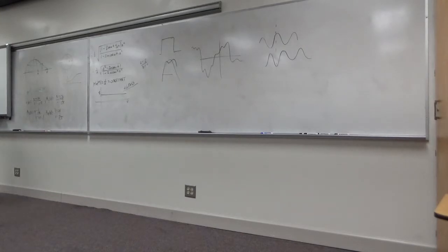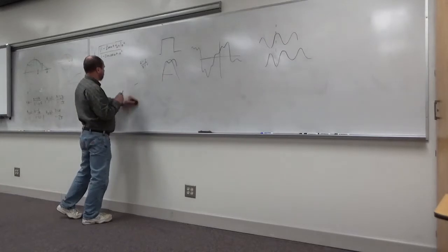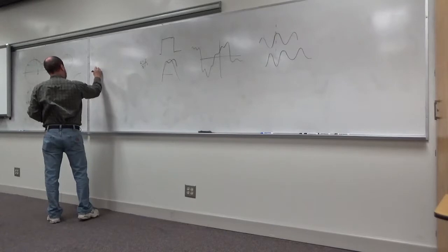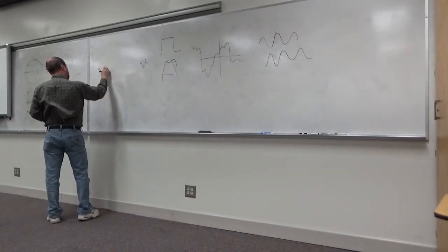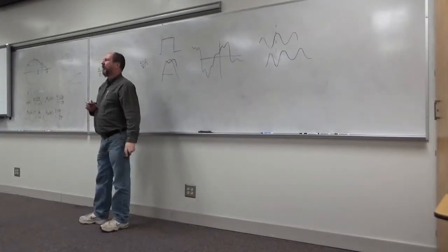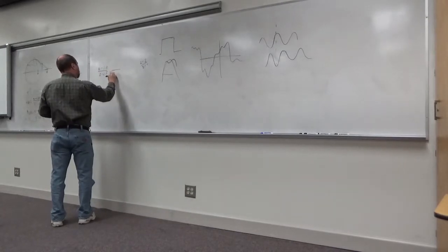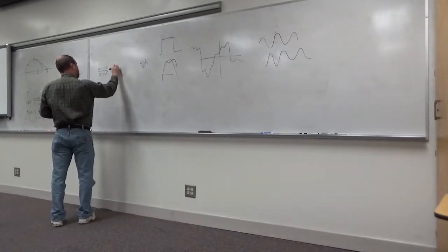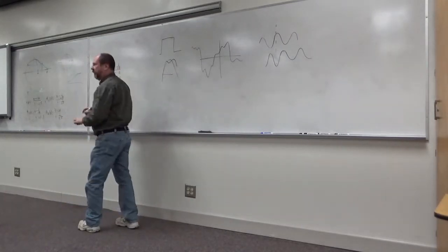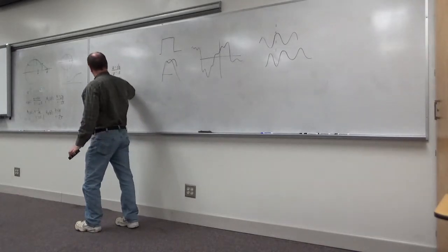Why? Because how could I get from the very first one? I just realized the very first one, that what I'm saying is not obvious. Z minus 0.5. Got a certain response. What if I multiplied it by this? Z minus 0.8, Z minus 1 over 0.8. What property does this filter have? All pass. That one's all pass.